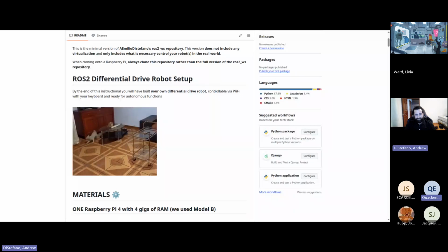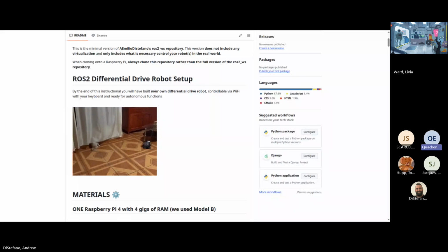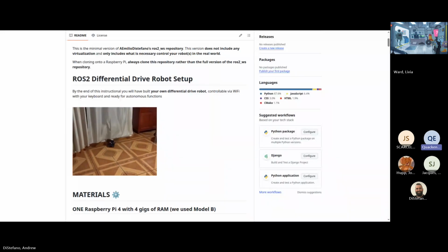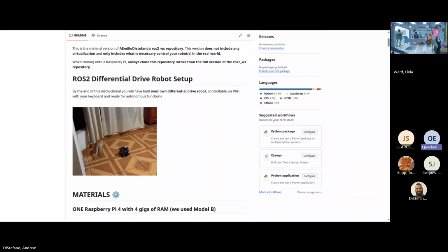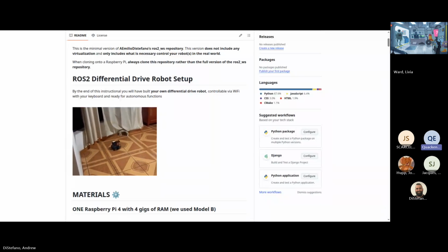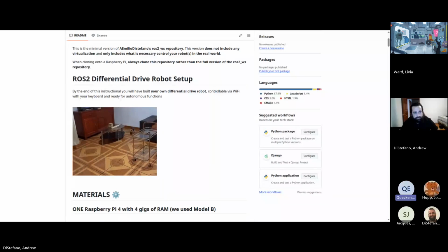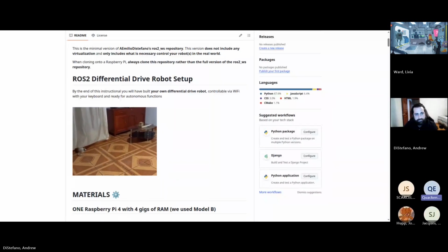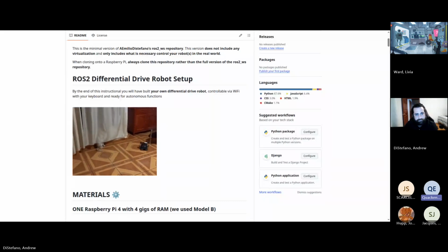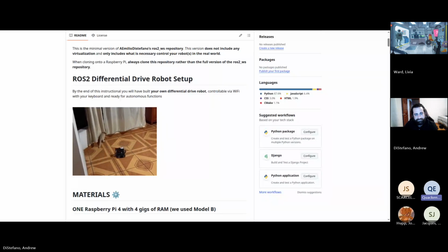Yeah, fascinating stuff. If you have the right antenna too, I have a feeling that some of the LoRa sensors we've been looking at have ceramic antennas on the PCB. I feel like those aren't going to have as long range as a monopole that is outside the body of it. If you want the longest range, you concentrate the RF energy using a very directional antenna, and you point them at one another. I think that's how you get kilometers of range.